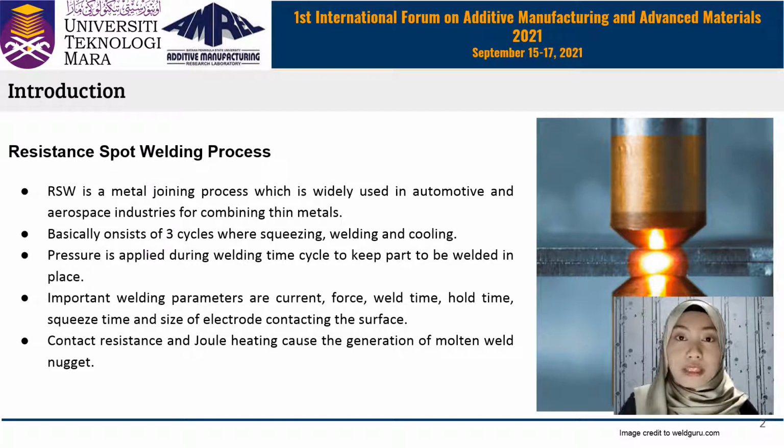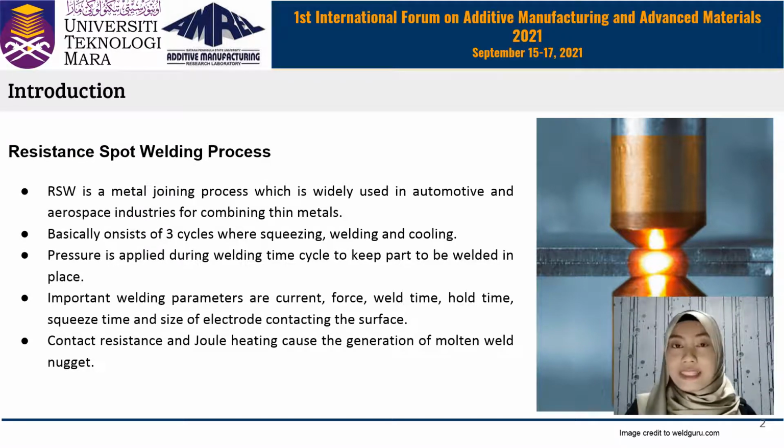However, if the thickness is more, it might be less effective. The spot weld technique was divided into 3 parts to provide the best results, which are squeezing, welding, and cooling. Each stage requires the definition of a few additional parameters such as squeeze time and electrode time during the squeeze phase, weld current and weld time during the welding phase, and electrode hold time during the cooling phase. Electrical and thermal conductivity, on the other hand, is a crucial consideration in spot welding.